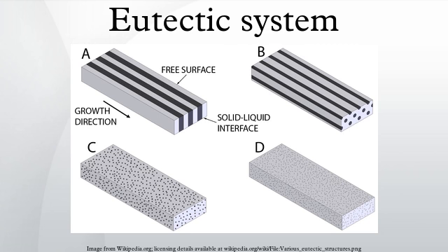Some uses include eutectic alloys for soldering, composed of tin, lead and sometimes silver or gold, especially the Sn63Pb37 alloy formula for electronics; casting alloys, such as aluminium-silicon and cast iron. Silicon chips are bonded to gold-plated substrates through a silicon-gold eutectic by the application of ultrasonic energy to the chip. See eutectic bonding. Brazing, where diffusion can remove alloying elements from the joint, so that eutectic melting is only possible early in the brazing process.